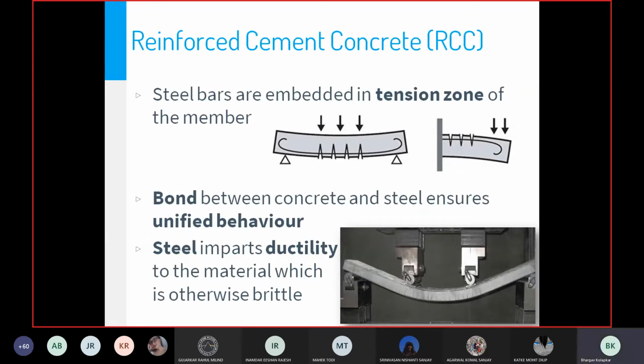In scientific terms, the coefficient of thermal expansion is the amount of expansion that you expect a material to undergo after increasing its temperature by, say, 1 degree. This coefficient of thermal expansion of concrete and steel are very close to each other. So, when reinforced concrete is subject to high temperatures, both of them expand together, and when they're subject to low temperatures, both of them contract together.